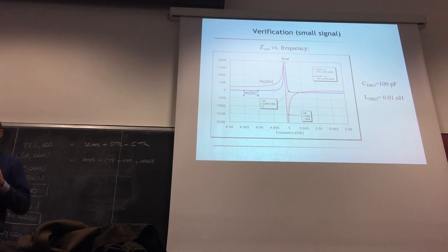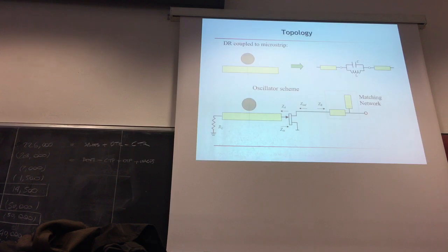This is the representation of the output impedance observed at the output of the active device. We know that oscillation can happen only when this impedance has a negative real part. So if the range of frequencies where the real part is negative is very small, we know that also the range where the oscillating frequency can happen will be very small. And so the system will be stable.